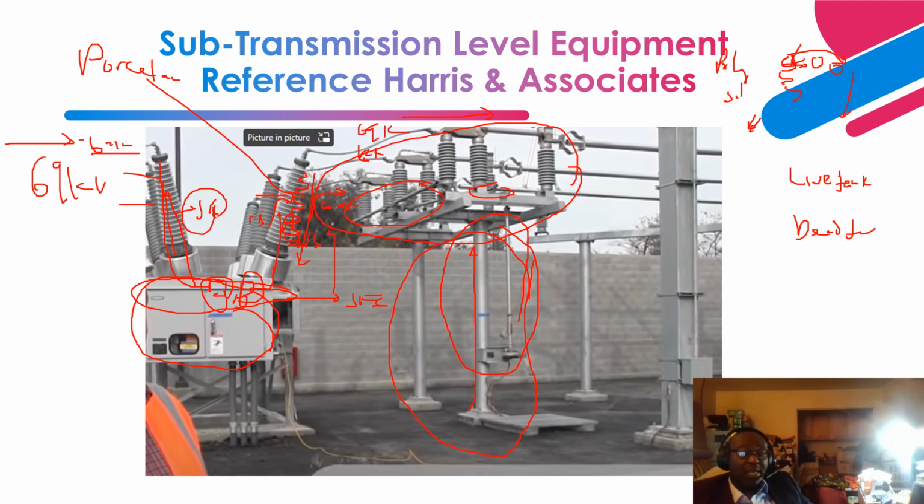The operator comes in here and steps on this ground mat. Okay, so this ground mat is to prevent static charges, shock, and voltage buildup, right? So if the operator is supposed to operate this disconnect switch, let's say open it or close it, the operator, as required by the safety guidelines, is to stand on this ground mat. They call it a ground mat, and operate it, right?